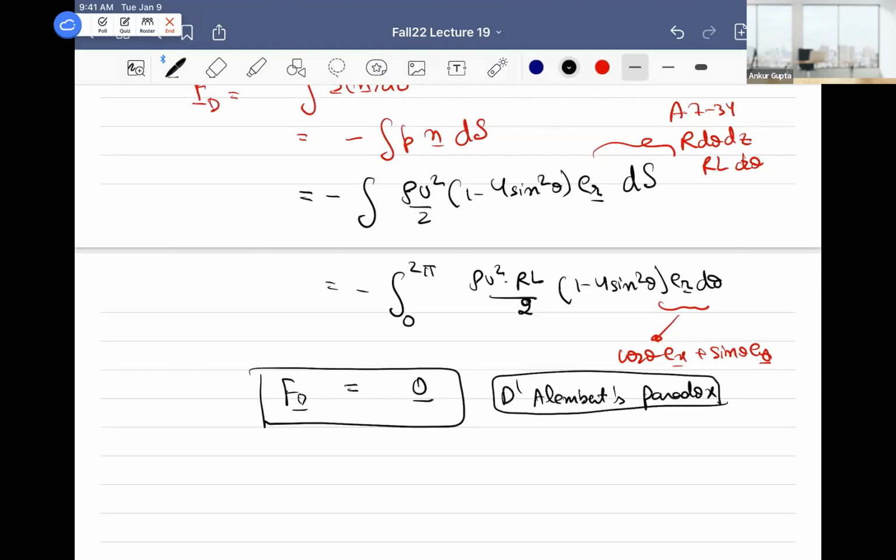And that's the portion of our next part of the course, where we go into boundary layers, momentum boundary layer, heat transfer boundary layer, thermal boundary layer. So that is what we'll discuss next time. But that's why this is wrong: viscosity is assumed to be exactly zero. It's never exactly zero. It is small. So Reynolds number infinity is not a number. When we calculated for a car, it was 10 to the 6. 10 to the 6 is not infinity. That means the viscous stresses are small, they're not zero. So that small factor changes everything. And by the way, this solution is still valid, but it's just valid outside the boundary layer. We'll discuss some of these things in the next part of the course.